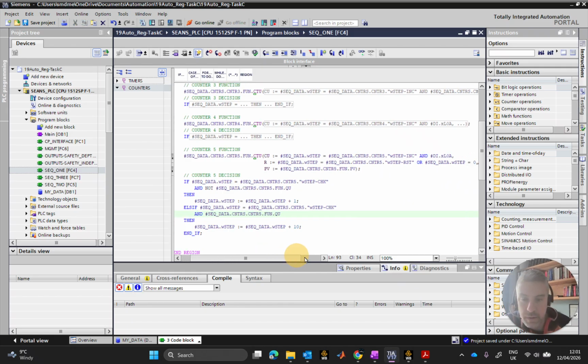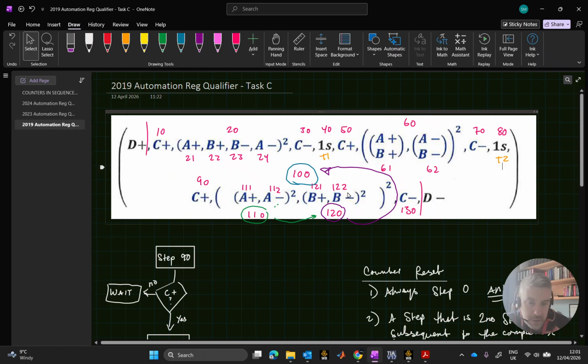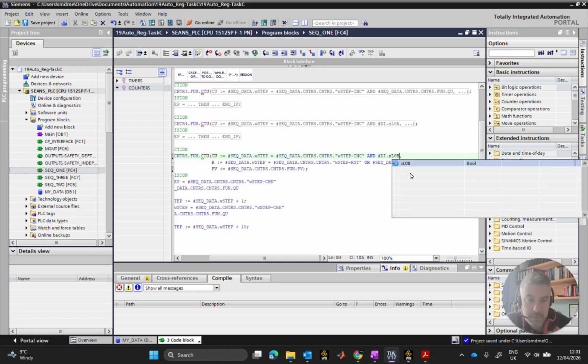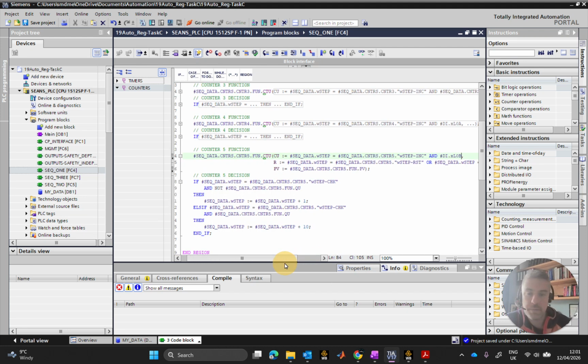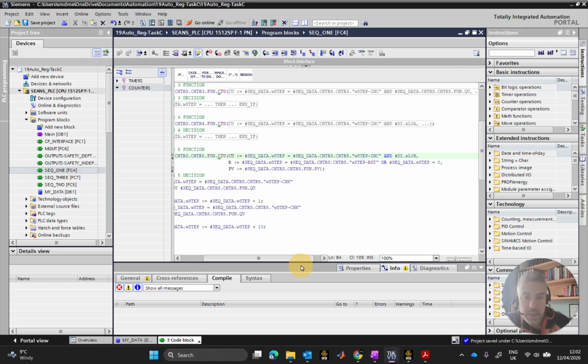There's a 5th counter. So what am I counting in my 5th counter? It's LOB. So I'm on 120, so 120, 121, 122. I'm going for LOB in my increment step. The reason I don't need to change anything in this is because I'm addressing that to my data block counter 5, which I put in that detail before we did anything. It's the first thing we did before we went into the outputs. We went into my data block and put in those parameters. And all that there is good.